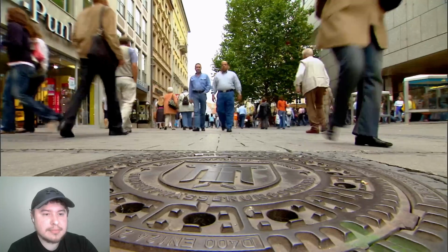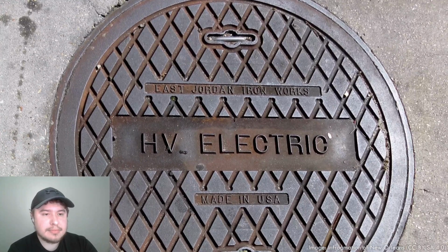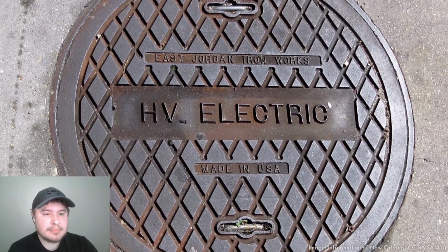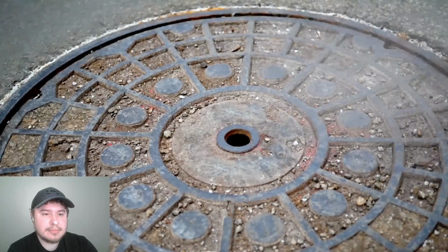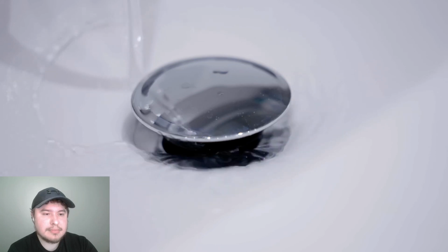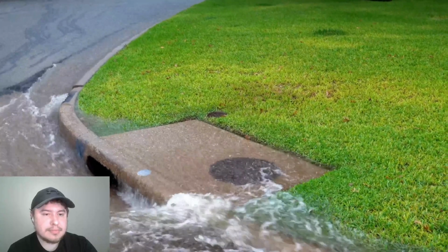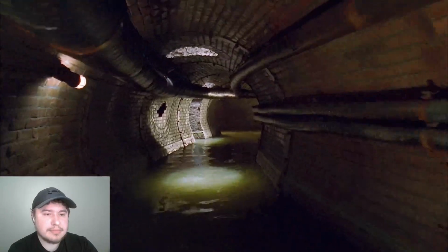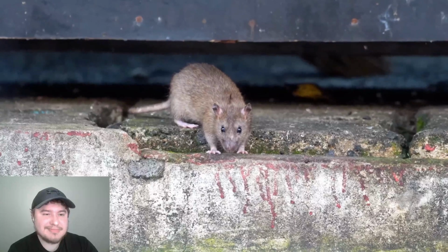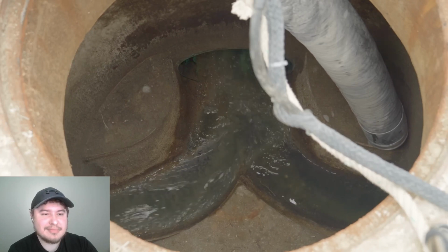There are lots of kinds of manholes. If it's a utility of any kind and you put it underground, there's a good chance you'll need some access to it at some point in time. But I figure if you picture a manhole in your head, it probably leads to a sewer system. Either a sanitary sewer that connects to your drains and toilets, a storm sewer that connects to storm drains, or a combined system that carries it all. Unlike what you see in movies, most sewer systems aren't huge tunnels full of totally tubular turtles and their giant rodent mentor. They're mostly just simple pipes sized according to the amount of flow expected during peak periods.